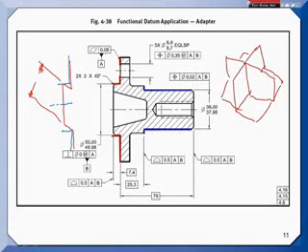Now, we take crummy features on the part. Crummy features. They're not perfect. We call them datum features. And we use those features to take this part and align it to these beautiful planes. So here's your datum, and they are mutually perpendicular, and they're considered to be perfect. They're theoretically perfect. But we use crummy features on the part to line the part up to those planes as best we can. Is that what you were after?